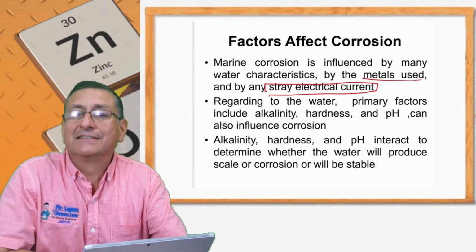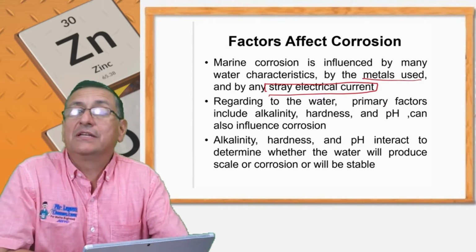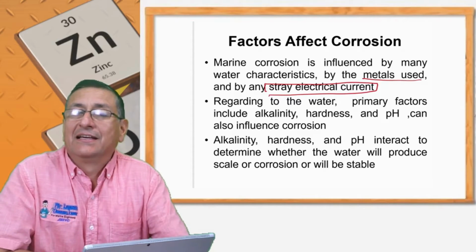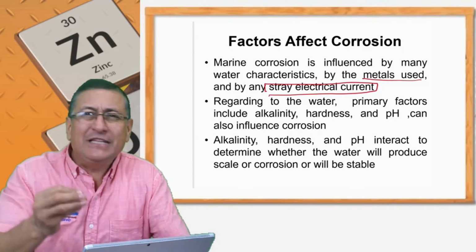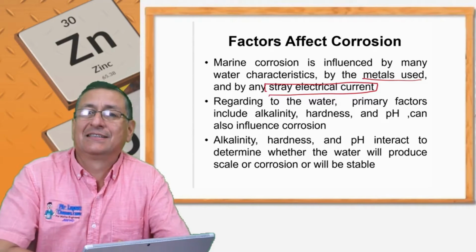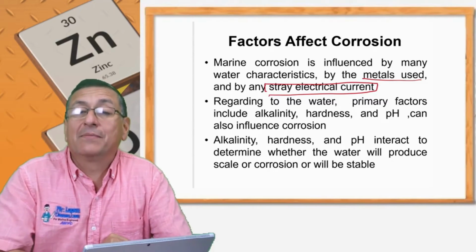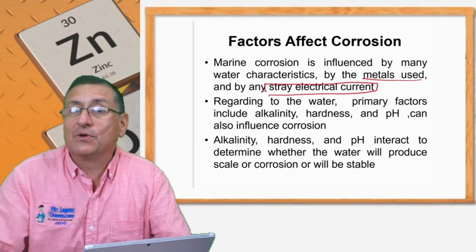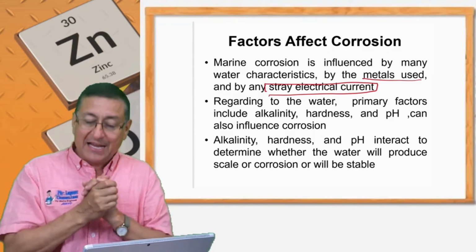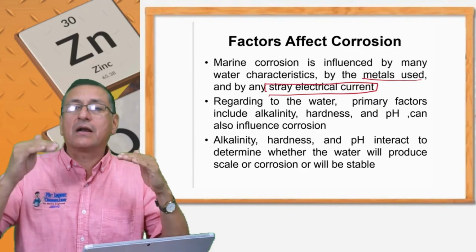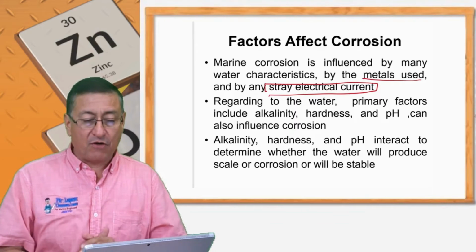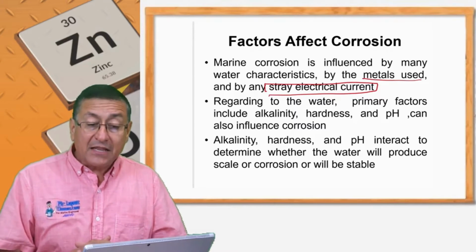Yes, this is the static electricity, and this is the worst scenario. For that reason, the bonding is critical. All the metallic elements inside of the boat should be connected with the bonding, and we are going to talk later about that. Right now I feel that we are moving faster in order to understand the phenomenon of corrosion. Regarding the water,